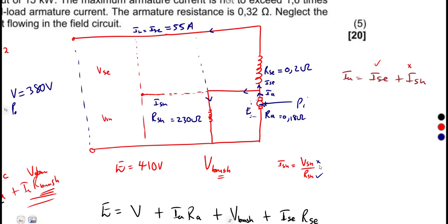So you see, guys, we are so much limited. So where can we calculate V shunt? V shunt and the series are the ones adding up to the V that you're given. So to find V shunt, we use V, which is equal to V series plus V shunt. So we can say V minus V series is equal to V shunt.